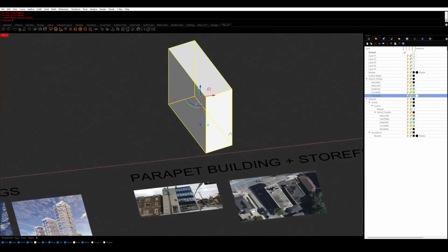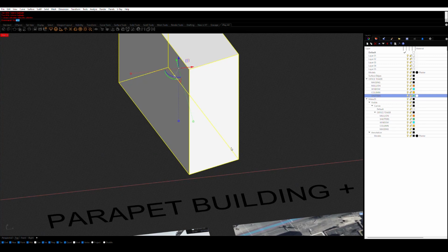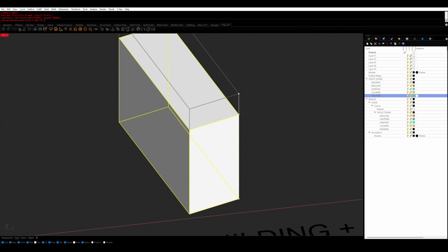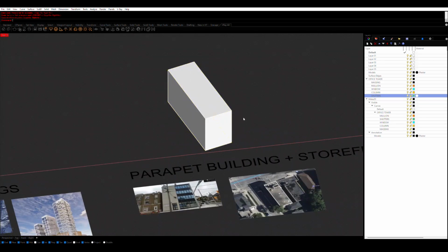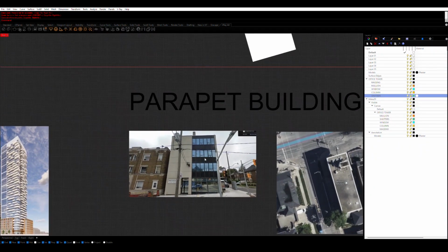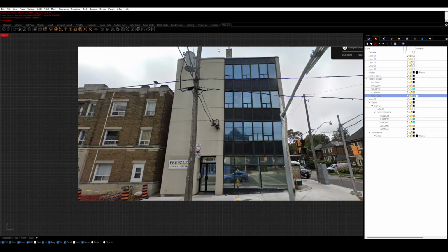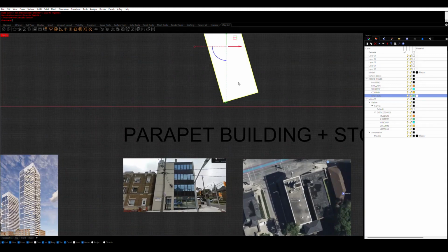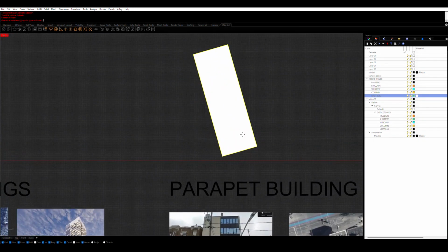So I've already made a basic massing for it. What I'm going to do first is reduce this to maybe 48 feet. That's like 4 stories. And we'll notice that it's approximately divided down the middle, maybe offset by like 2 feet, 1 foot or something. One side is quite plain and the other side has all these windows. So we'll do that first.